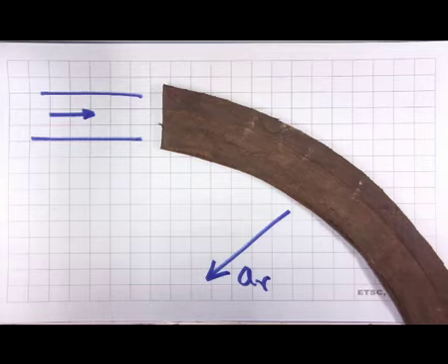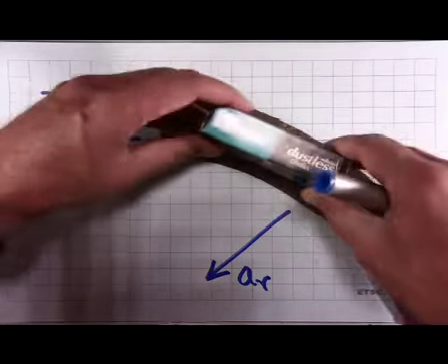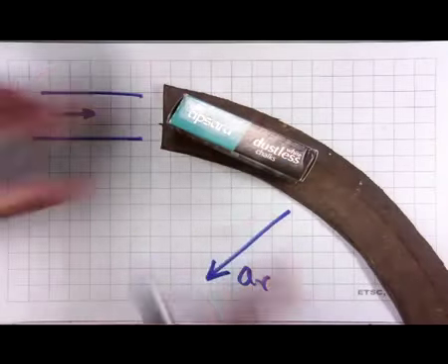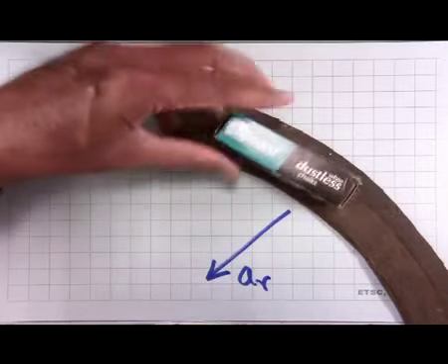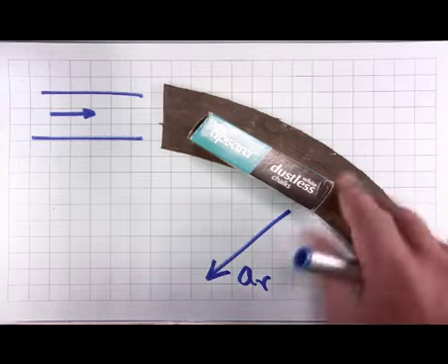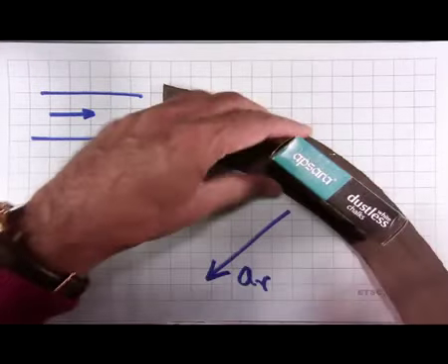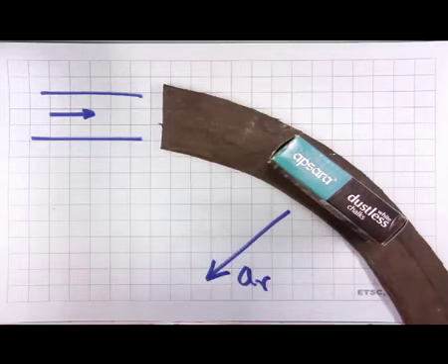And this radial component of the acceleration is what is provided by the friction. In this case, we will assume that the friction force in the direction of motion of the car, that is in the tangential direction, is neglected. But just to provide this radial component of acceleration, a friction force has to be there in the radial direction also.